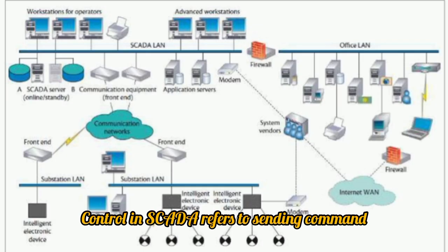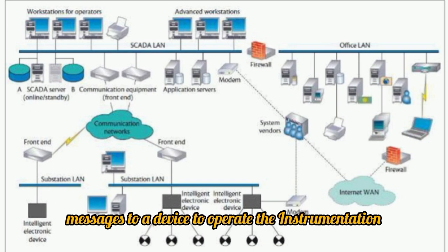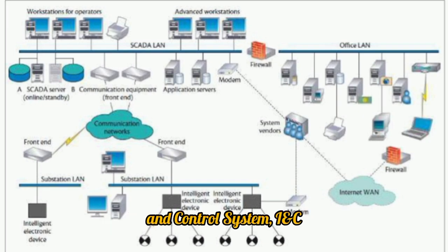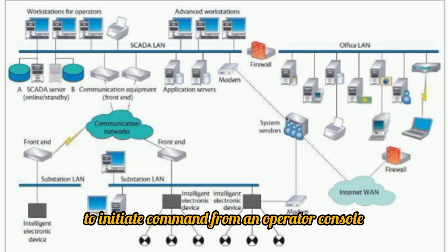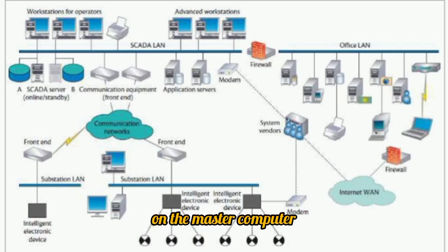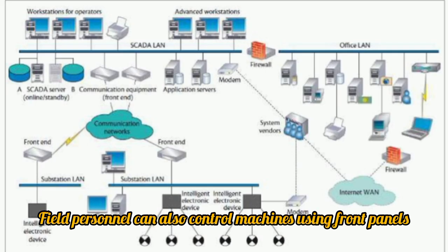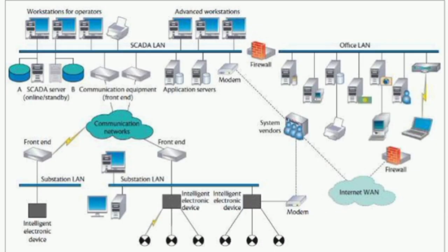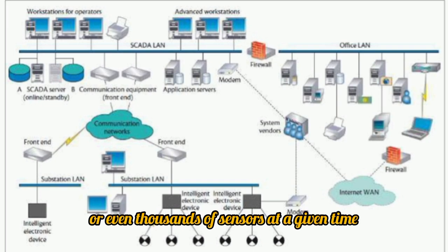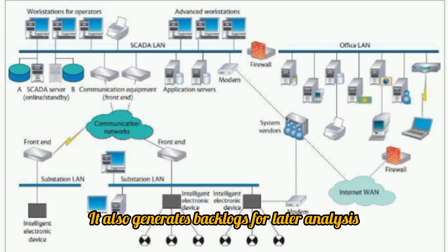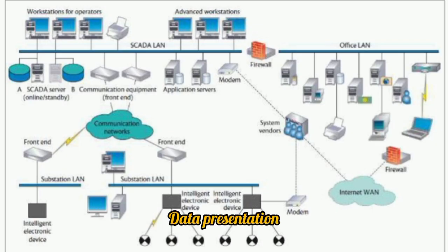Control. Control in SCADA refers to sending command messages to a device to operate the instrumentation and control system, I&C, and power system device. Conventionally, SCADA relies on human managers to initiate commands from an operator console on the master computer. Field personnel can also control machines using front panels. Data collection. Instead of filling data sheets, SCADA compiles information in real time. SCADA gathers data from hundreds or even thousands of sensors at a given time. It also generates backlogs for later analysis.